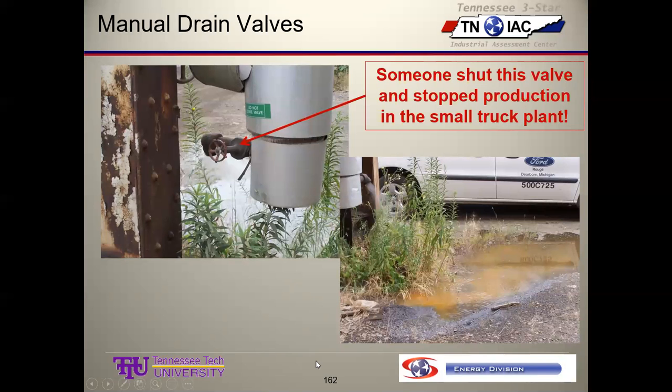They're running 40,000 horsepower worth of compressors. One central compressor building. They had no dryers. I couldn't believe it. Everybody in our team just looked around. What do you mean you don't have any dryers? No dryers at the point of compression.